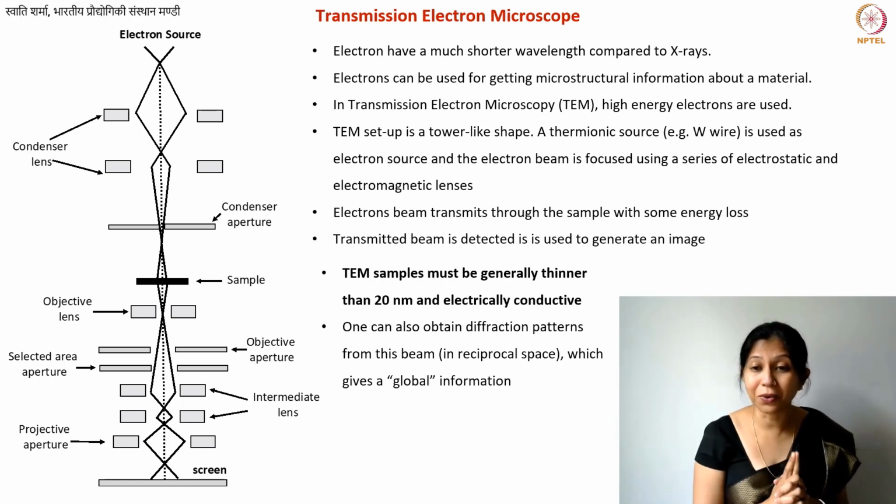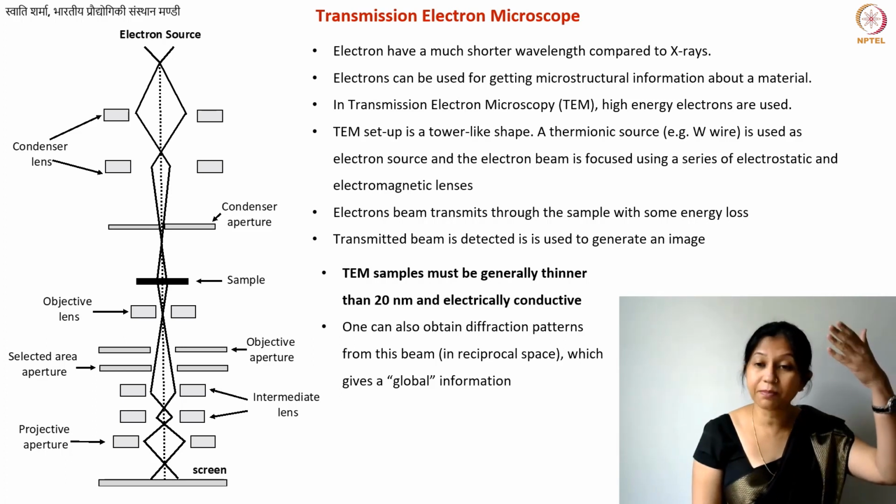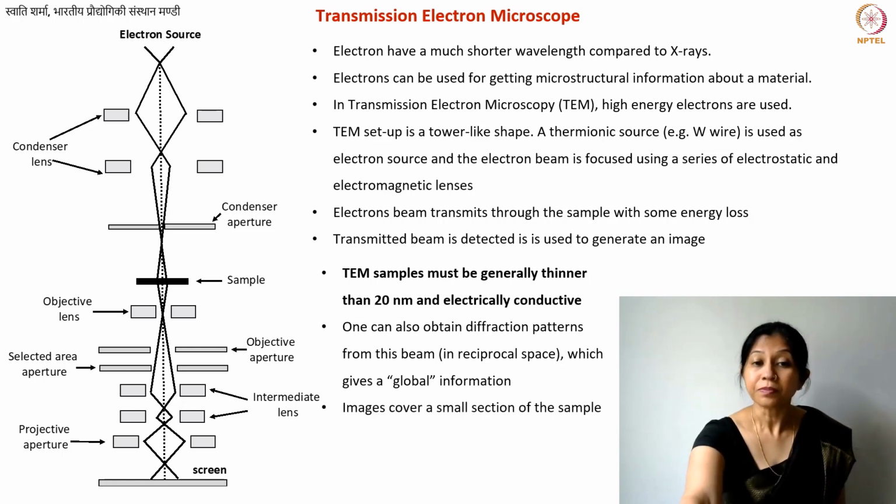Non-graphitizing carbons, you know that they are turbostratically arranged and their sheets contain defects and so on. In that case, what is missing is the 3D crystal structure. So we have crystals in 2D, but the 3D arrangement is missing. And whenever the 3D arrangement is missing, it becomes very difficult. Even with XRD, it is difficult. But potentially you can get electron diffraction patterns as well using your transmission electron microscope.